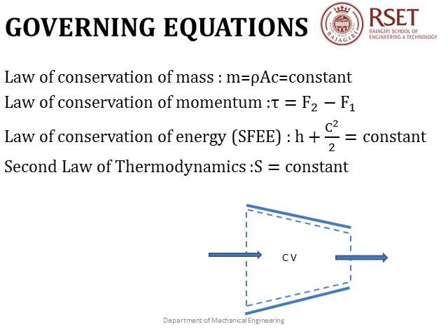If you refer back to the adiabatic energy equation, we see that at a particular point in the fluid, the sum of enthalpy and kinetic energy gives us the stagnation enthalpy. Combining these two results, we can say that stagnation enthalpy H0 is equal to a constant for an isentropic flow.